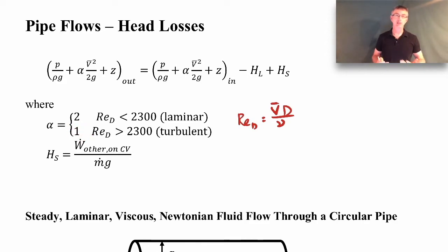And the reason for that is because the velocity profile for a turbulent flow looks a lot closer to an average profile because it's been mixed and it's more uniform and more blunt shaped, and so it looks like an average velocity profile, and that's why we get closer and closer to a value of 1 as the flow becomes more and more turbulent.